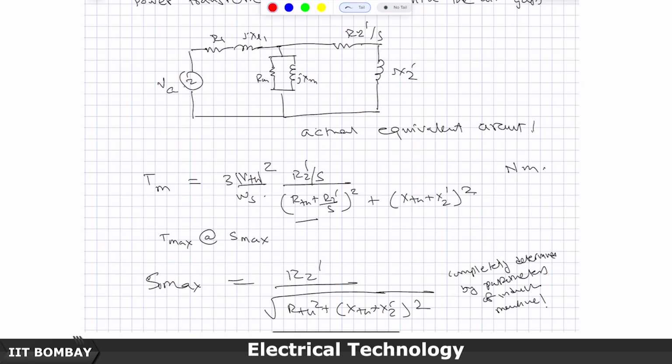And if the induction machine current is 4 to 6 times, voltage drop will be there significantly, because a lot of power is going to be sucked out from the lines which are coming to your home. So, at your home terminal itself, or wherever you are, industry or wherever, you will see a dip in the voltage, and that dip in voltage can cause flicker in the light.